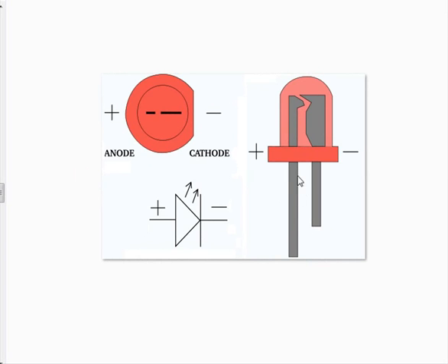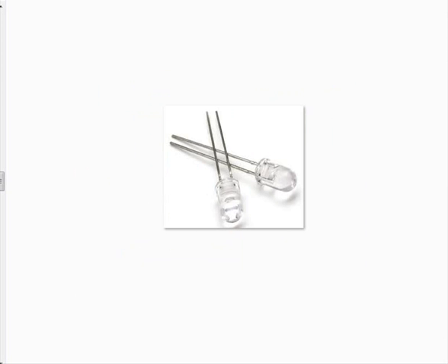An LED goes defective mostly if the leg is short and you apply more heat during the soldering. So be careful while soldering this active component, which is very sensitive to heat.